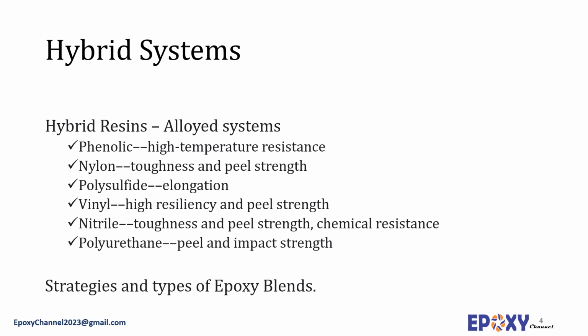For example, with phenolics for high temperature resistance, with nylon to add toughness and peel strength, with polysulfide to enhance elongation, with vinyl to reach high resiliency and peel strength, with nitrile for toughness, peel strength and also chemical resistance, with polyurethane to enhance peel and impact resistance.